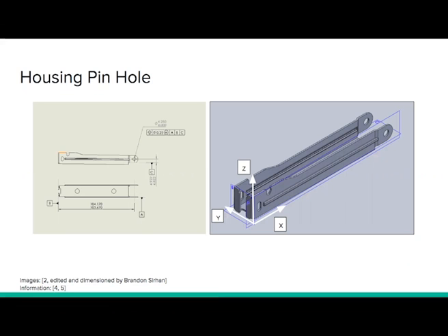In selecting the tolerances, two main factors were taken into consideration: the manufacturing process used to create the part and the scale of production. The most predominant manufacturing process used in creating stapler parts, specifically the metal housings that make up staplers, is metal stamping. This process is capable of achieving high repeatability and accuracy when piercing a hole within a tolerance of roughly plus or minus 0.05 millimeters.